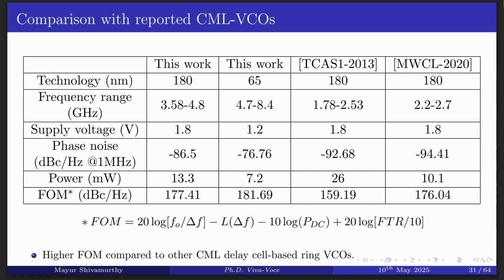The proposed VCO architectures were compared with reported CML based delay cells. Considering the figure of merit, where higher is better, which accounts for the power dissipation, offset, phase noise, as well as the frequency tuning range, the proposed VCO shows a better figure of merit compared to other CML delay based VCO architectures.